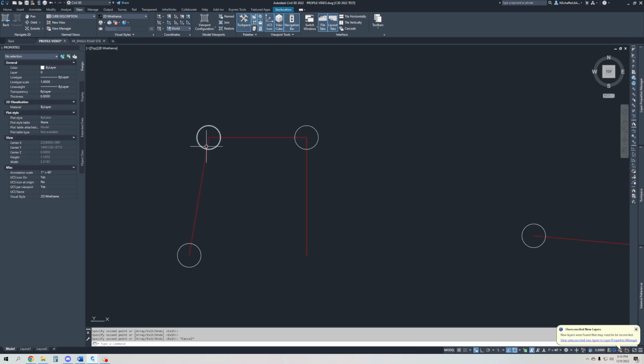Then I would typically, so in the city that I live in, the standard for the shape of this curb would be 1 inch in distance between this point and this point. So what I mean by it would be 1 inch this way, in the east-west direction, I guess, if you want to use your view cube. So I would draw this point or this point, whichever one I draw first, and I would either use a stepped offset or another way that I'll show you here momentarily.